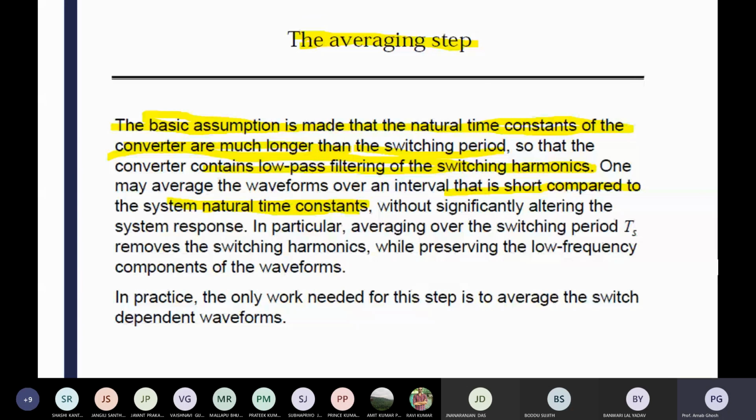That's why the time constant is more important. The time constant is an important consideration, a prerequisite for converter controller designing. If the time constant is much smaller than your design value, the response will be very fast and die out very fast, but the problem is stability issues, you will not get good stability.